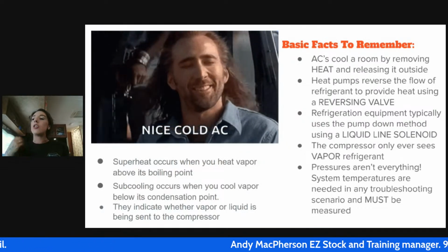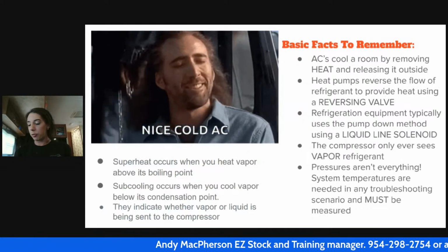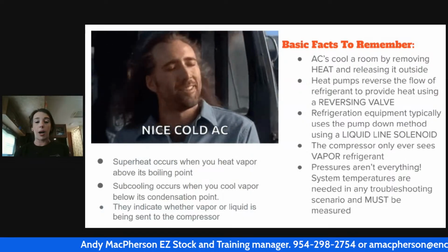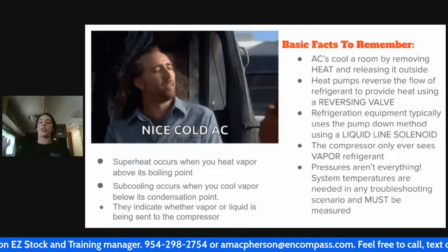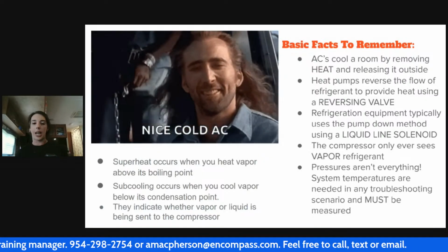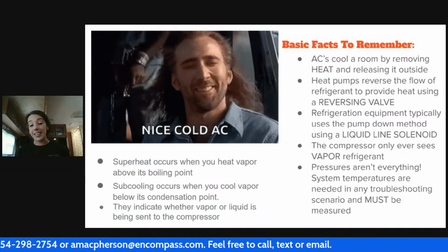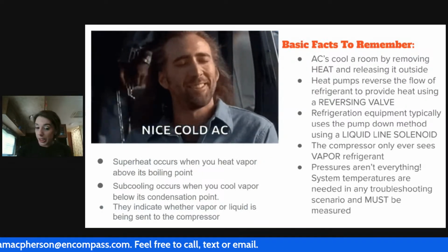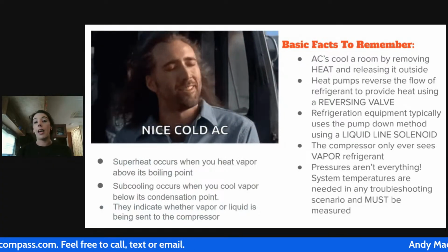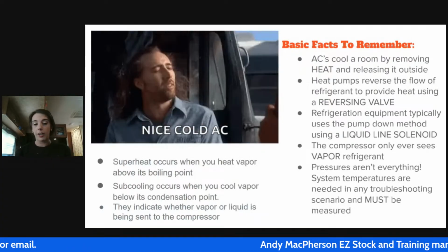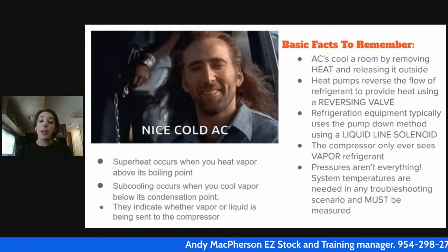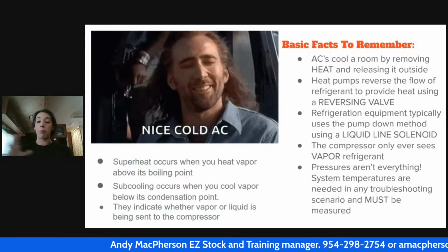So if we get into a habit where we don't know how to read our gauges properly and we're rushing because our boss is on us, we need to get 10 service calls done today because we're just slammed. You're going to be here till midnight. And you accidentally misdiagnose a restriction for an undercharge, right? And so you gas and go it. You put some more refrigerant in it. Makes perfect sense, except that now you have flooded that compressor, and now that compressor is not going to last.